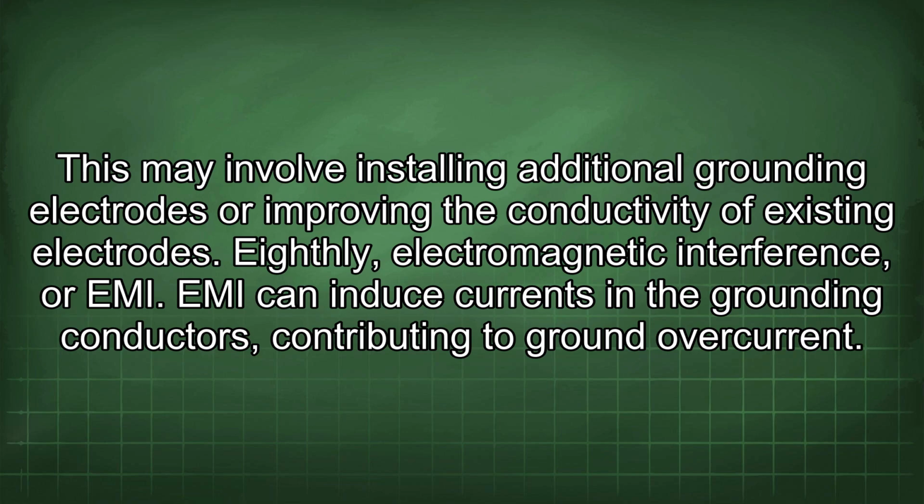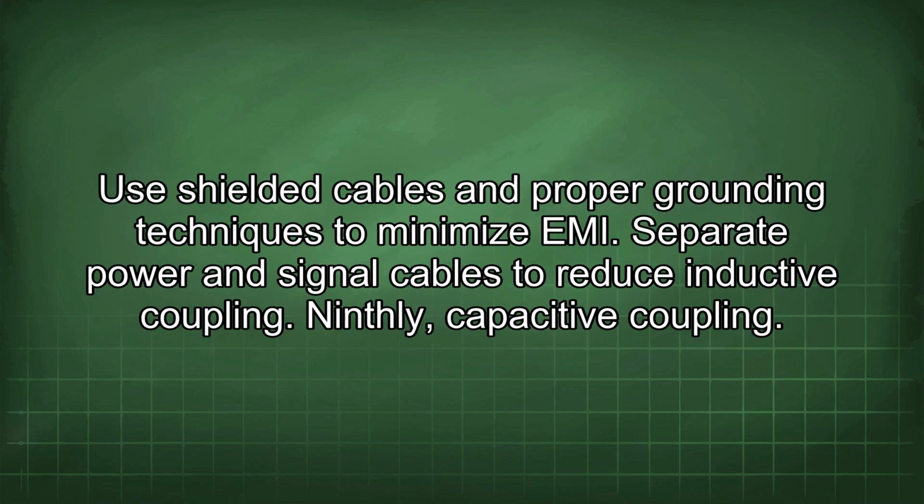Eighthly, electromagnetic interference, or EMI. EMI can induce currents in the grounding conductors, contributing to ground overcurrent. Use shielded cables and proper grounding techniques to minimize EMI. Separate power and signal cables to reduce inductive coupling.